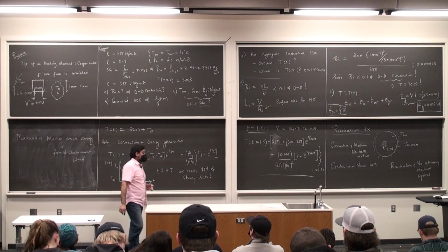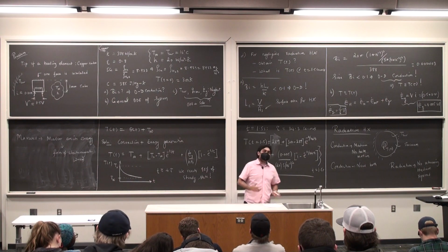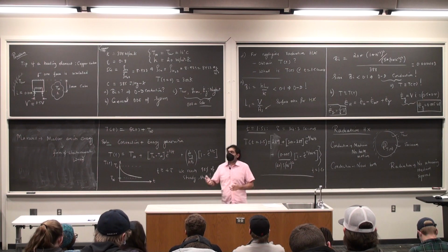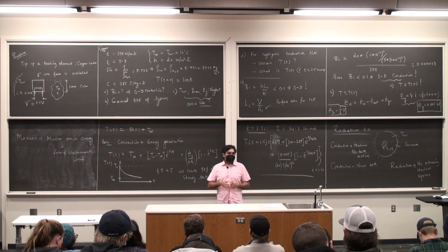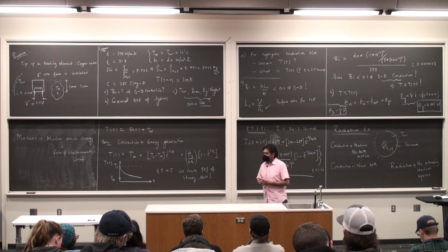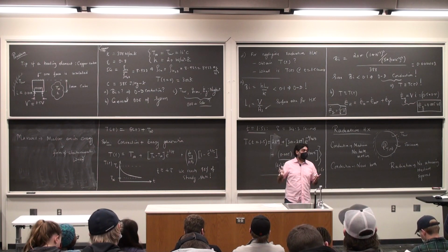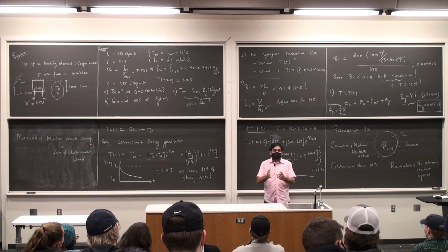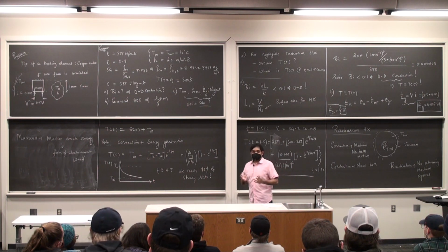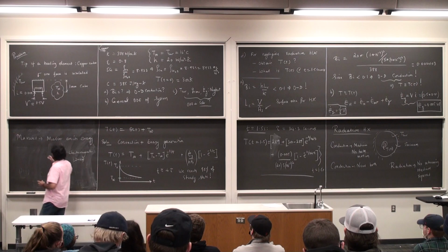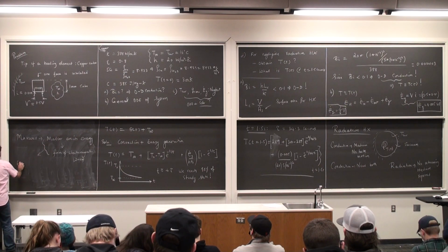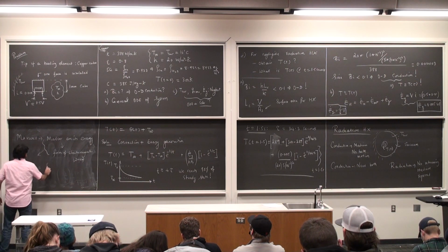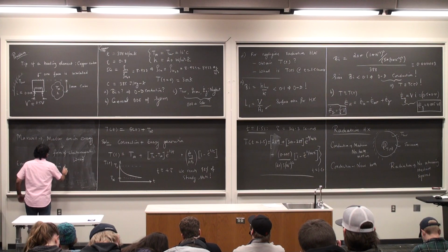Okay? And because the energy is emitted and transmitted in the form of waves, it is quite obvious that the intensity of the energy emitted should be a function of the wavelength of these waves. And so it behooves us to study, first of all, the entire electromagnetic spectrum, which contains a whole list of wavelengths, and then we will slowly shrink it to a region of interest for us as mechanical engineers. Okay, so this implies that the energy emitted is a function of wavelength.